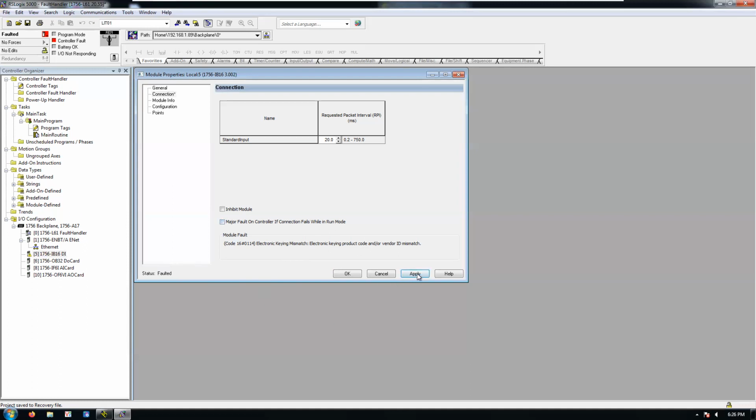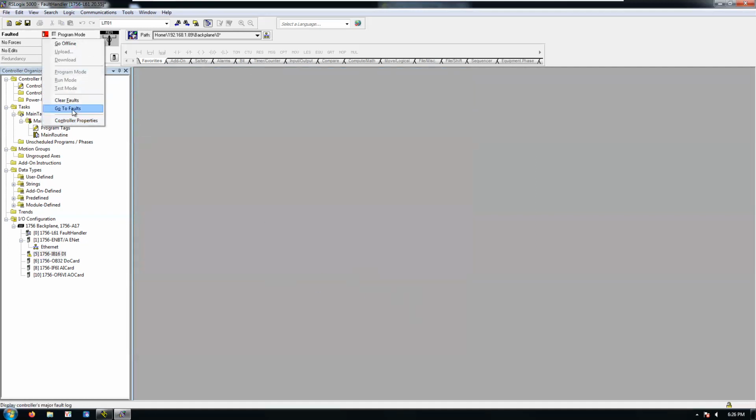If you've got a card that you can allow to fault, well, turn it off, hit OK. We can clear the fault and we can continue on our way. It'll run with this error here. So you can see we've got a flashing IO not responding issue. If this were still allowing all of your inputs to work, you could let this run like this. If any of your inputs were not working properly, that might be something you would need to address. If you can't trust your IO cards, you can't trust your process.